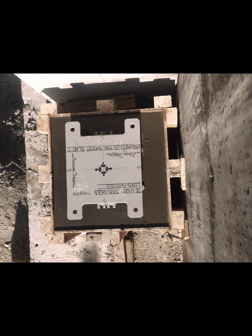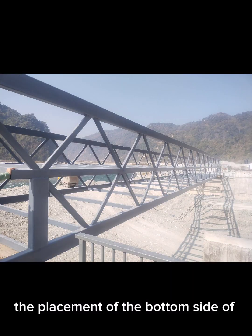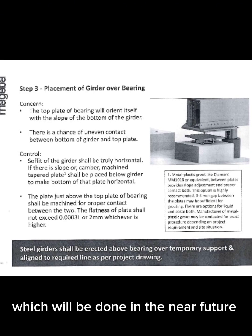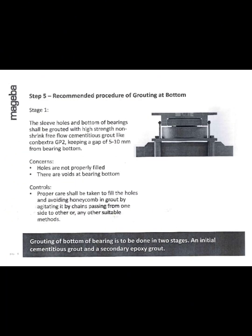After the placement of bearing and casting of the pedestal is done, the pedestal is left for the curing effect to take place. The next step will be the placement of the bottom side of the girder on the pedestal, which will be done in the near future.